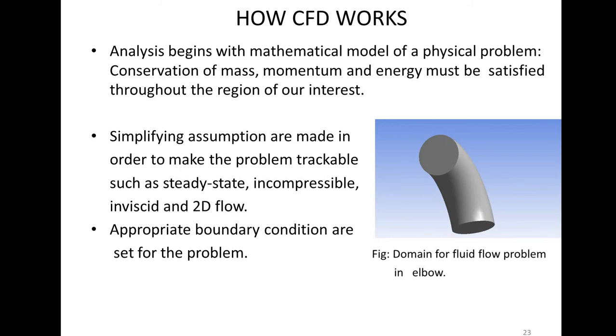If it is a steady state, why make the computer rely on extra work? We state it is a steady state. If the fluid is almost incompressible, we state it is incompressible, inviscid if it has no viscosity, and if there is no reason to work with height or any other dimension, we can consider only 2 dimensions. So it will be easier for the computer to solve, and we can also save our time as well as computational cost.